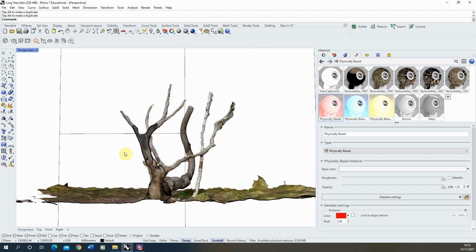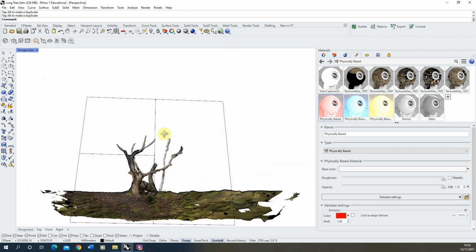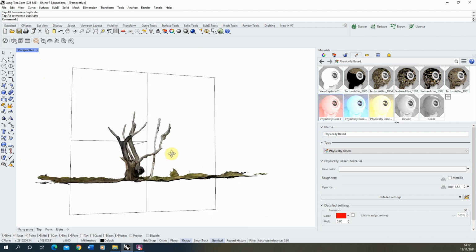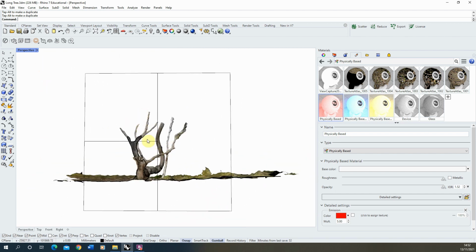Now what you would usually do if you were doing a section of a model that was made in Rhino is you might then do a Make2D of this particular piece. Now with these really dense meshes, I would advise against doing Make2Ds of these.